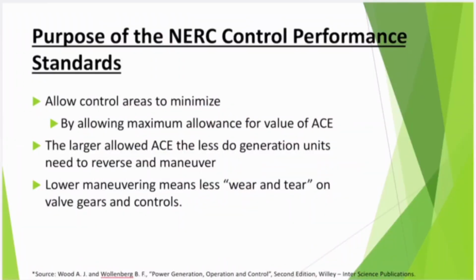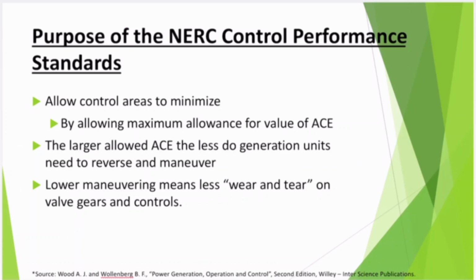If you pressure your generators to behave in a ramp way, that suddenly you give me 100 megawatt, suddenly you reduce your generation by another 50 megawatt, this is not practically acceptable, though theoretically it is possible. So based on ramping capability, only a minor change is acceptable. To make my machines robust and my system operational and reliable, we allow a certain variation in my ACE, and that is governed by certain standards.